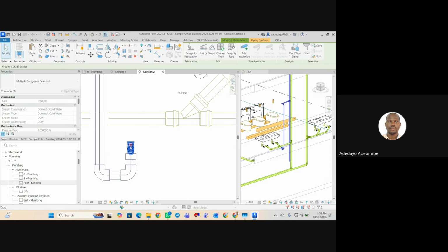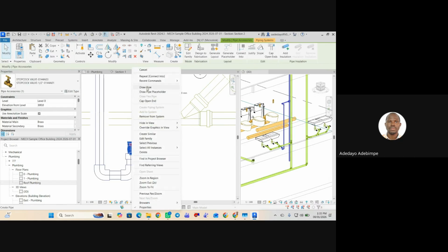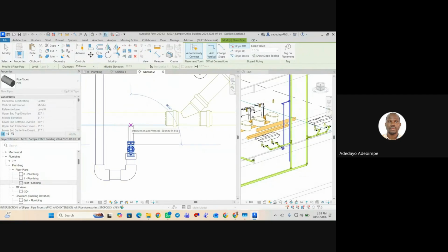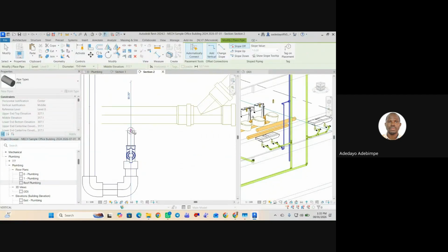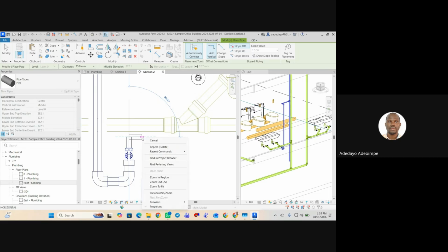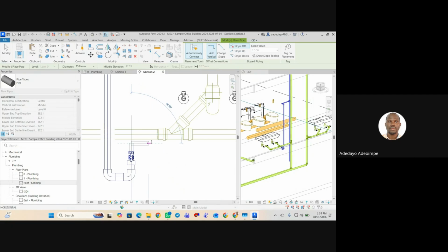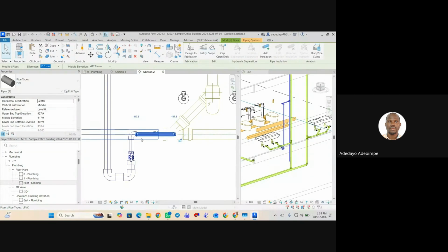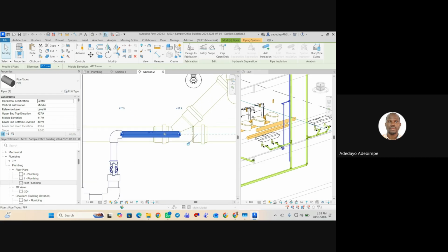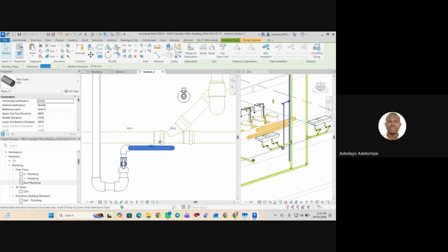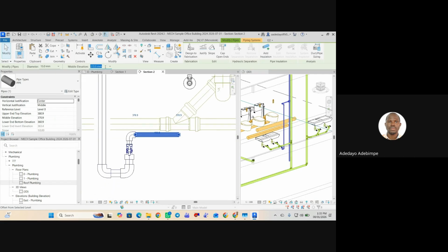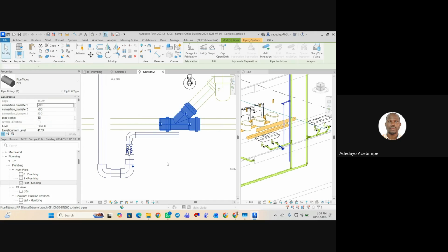Now, I'm also going to have a pipe that will now come out to low level. So now, this is where Revit gets interesting. As you're modeling, you're also coordinating as well. Now, from my section, you see that if I route my pipe at, let's say, this 400 mm at low level, it's going to be clashing. It will probably clash with my waste pipe. So let's just do something a bit lower and say, let's say 370. I like rounded figures.